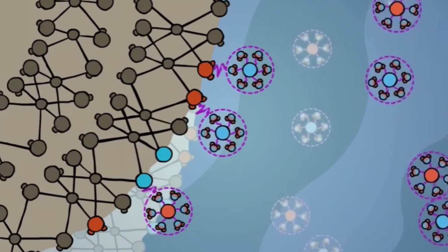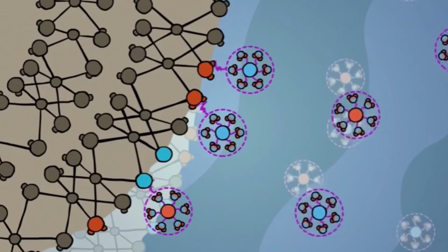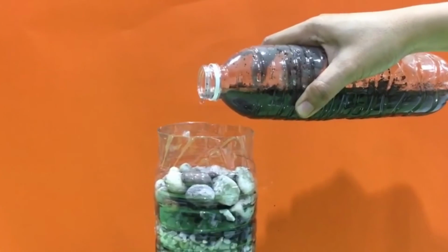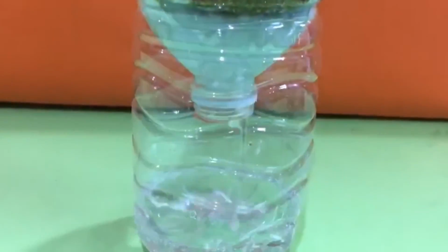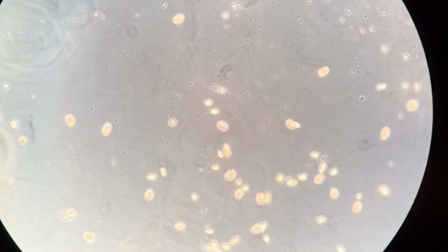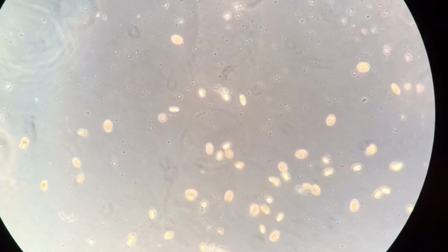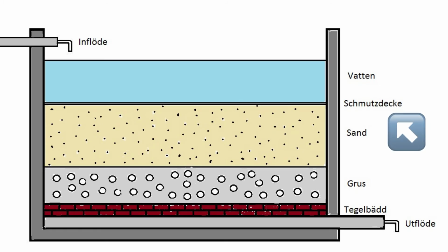Negatively charged sand may attract positively charged contaminants, causing adsorption. Slow sand filters, on the other hand, focus more on removing biological contaminants, mainly protozoa and bacteria, through a biological layer called Schmutzdecke. Microbiota of this layer helps to eliminate the biological contaminants.